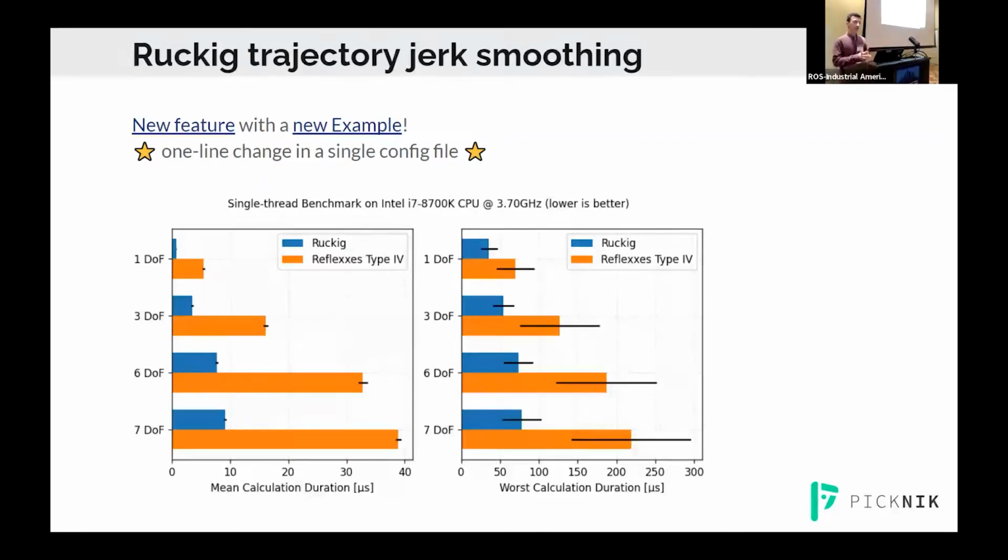And there's some nice stats here from the maintainers of Ruckig as far as you can run this very quickly in the loop. So there's also been some investigation into running this at a visual servo level and not just at a trajectory parameterization level. So if you're working with large equipment, you can dynamically change where these limits are depending on what your payload is, which is also really nice for maximizing your cycle time while preserving the life of your hardware and not shaking it to death.